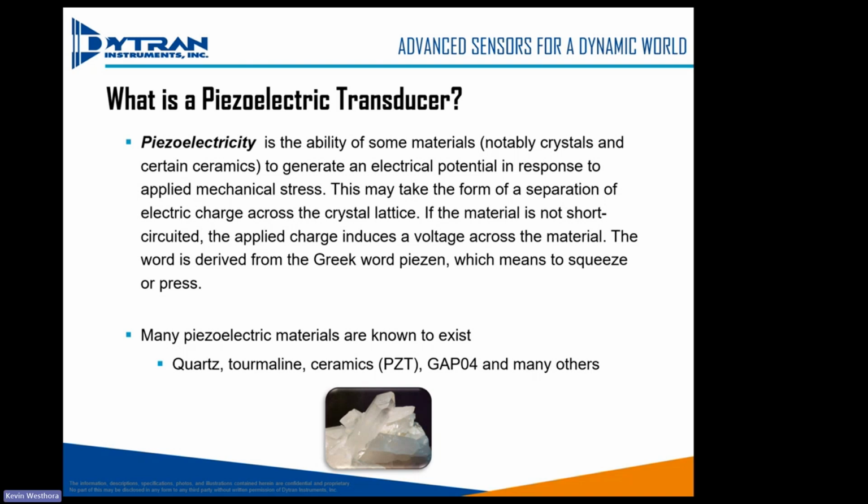So think of it like a sponge. If you see this crystal down here, if I squeeze that crystal, I get an electrical output measured in coulombs, and the size of that charge is so small that we measure it in picocoulombs, a very, very small amount of charge, but it's extremely linear. So if I squeeze a little, I get a little out. If I squeeze a lot, I get a lot out.